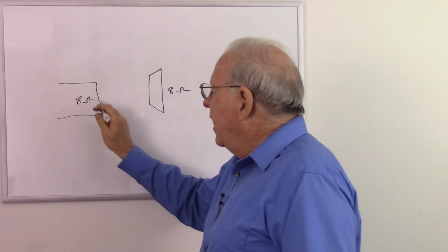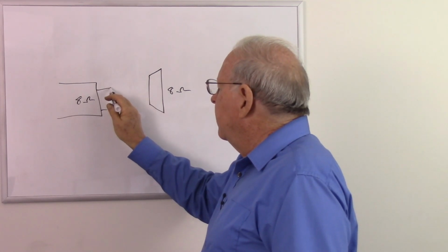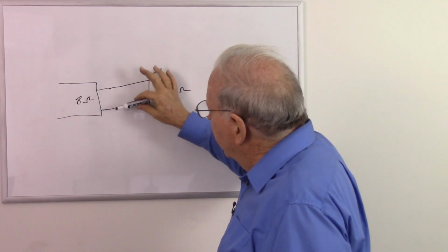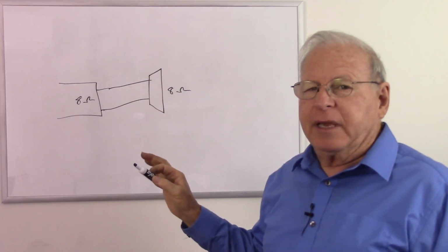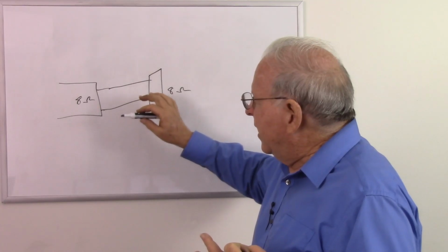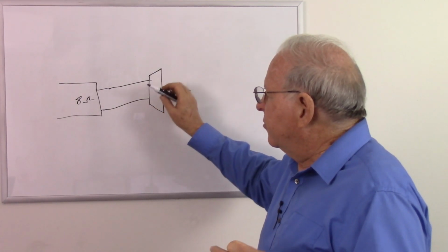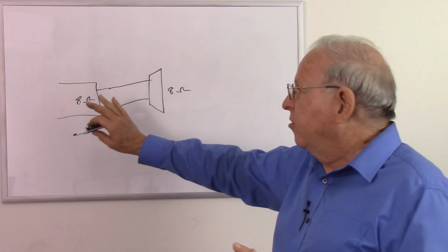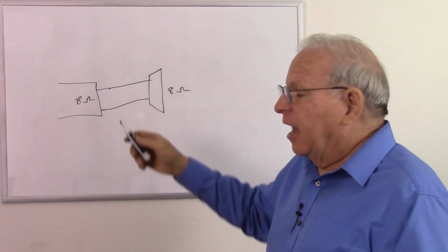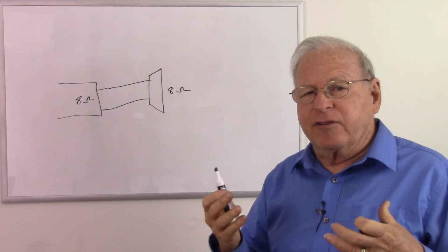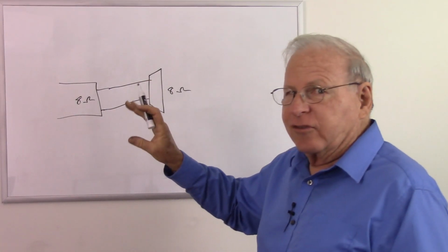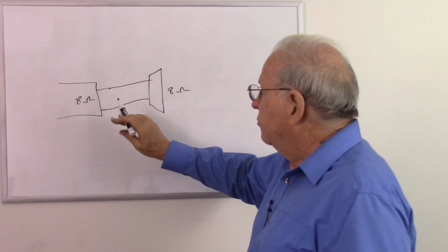8 ohms. And that's probably what you're going to see most often. The impedance of the wires here is inconsequential because at these frequencies, the impedance is much, much lower than the resistance, and this is very low resistance, so they don't even really figure into the equation like the feed line of radio where we have a different situation we'll talk about down the road. So we don't care about the impedance of the wires. That's going to be very, very low and inconsequential.